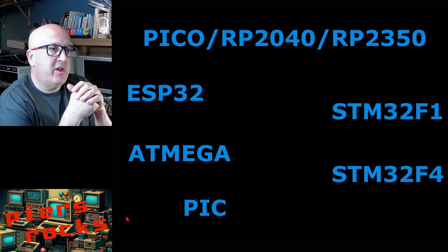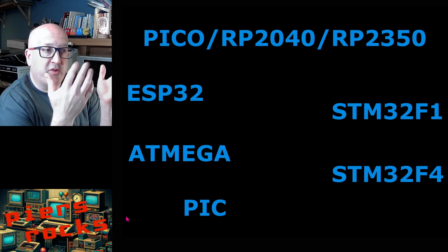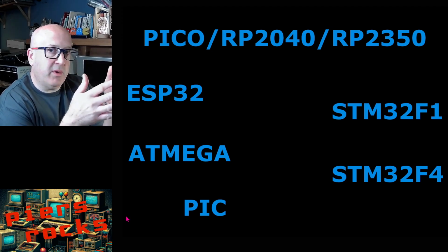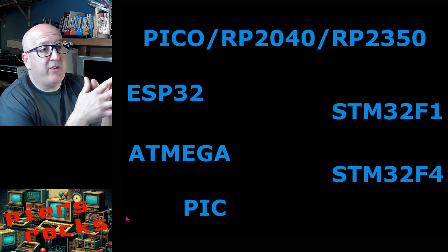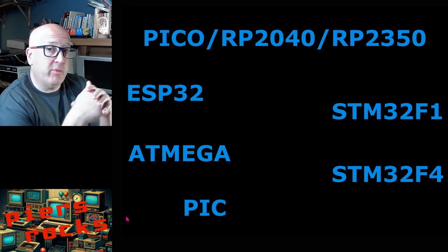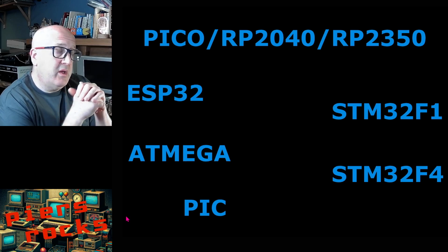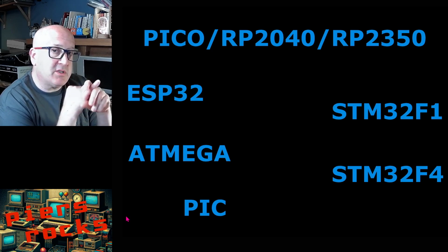Initially, I focused very much on the STM32F1, as I said before, because it's a much cheaper part. You can get them in onesie twosies from AliExpress for under $1, particularly if you're prepared to go with the Chinese clone variants. But it just doesn't have enough horsepower for this application. That's partly because the clock speed is a little bit too low. Again, I wanted to run this from the internal oscillator.